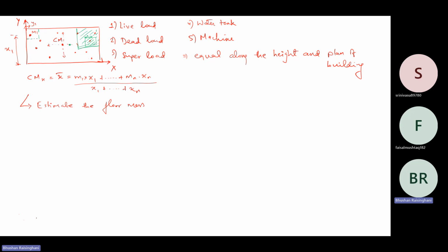And CM is the concept when rigid diaphragms are there. When there is a semi-rigid or a flexible diaphragm, the CM concept does not exist. The mass is distributed across the floor, it is not concentrated. And based on individual masses, like M1 you saw, or M10, where the column is coming, only that much portion will be transferred to the column.